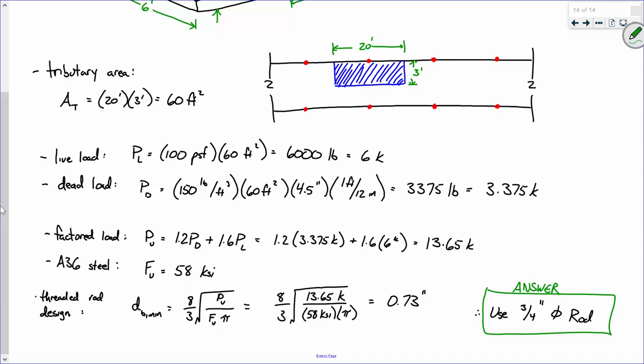That does not mean turn it into a library. Okay? This is an important point. If somebody were to come in and say, no, we're going to take all this and turn it into a full-scale library, well, a structural engineer would then need to come in and evaluate the floor system and say, well, can you really do that? This is a good point. I'm saying under its intended use, it's fine. You're talking about changing the use, and now that requires further investigation.